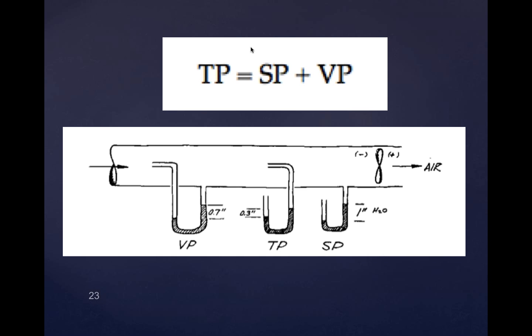If you imagine blowing up a balloon, that extra pressure that's in that balloon is all static pressure. It's not moving, but it is exerting pressure against the sides of the balloon. And it's the same pressure whether you're in the middle of the balloon, towards the left side of the balloon, or to the right. It's always the same pressure. Same thing in the ductwork. That suction pressure, that negative pressure, is acting throughout that duct at that point. Doesn't matter where you are.